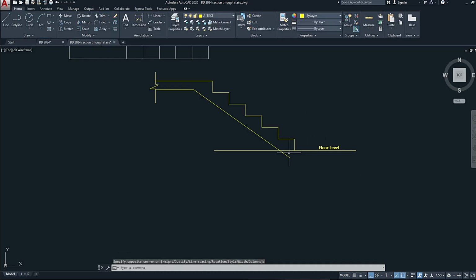All right. Now, because it's a section, you could also draw the footing for the staircase as well. I'm going to quickly mock up something here. I'm going to offset this. Well, I'm going to draw this line here down by about 2 feet, which is about 600 millimeters. I believe that's what I entered a while ago. Let me double check. 600 millimeters, and then I'll draw the pad footing similar to the one that you'll draw for your house. All right, so it will be 150 for the thickness, then down